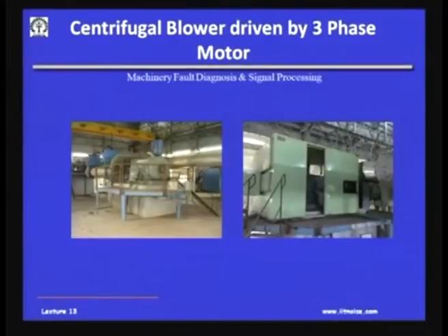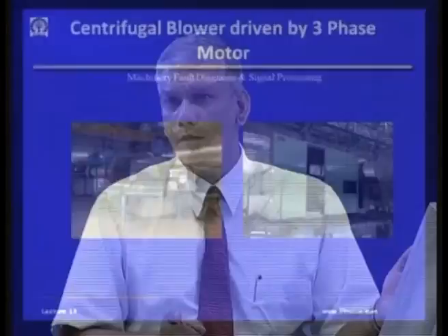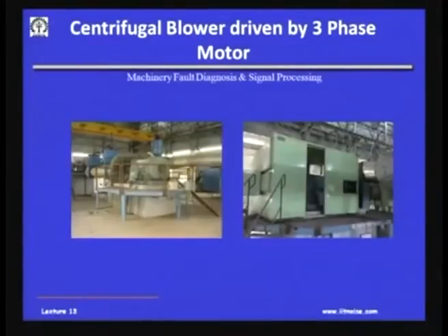And if you enter such a place, you will hear this kind of loud decreasing, increasing sound. If you go to any plant wherein many machines are supposed to operate at the same speeds, because of some reason or the other, if some machine is running at a little lower speed than the other, you will hear this kind of waning, waxing noise, which happens even in ship engine rooms, I believe, because there will be machines running not exactly at the same frequencies, and this happens in the blowers also, of course.